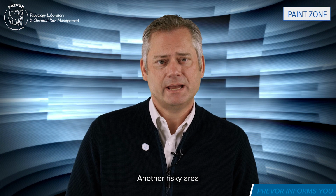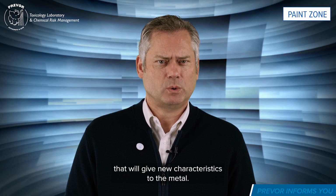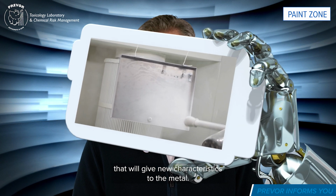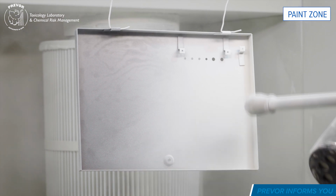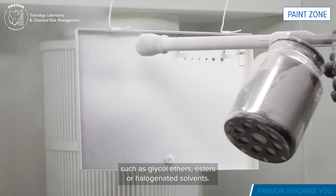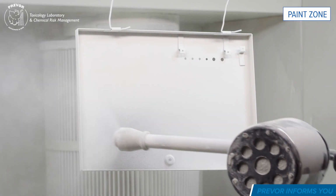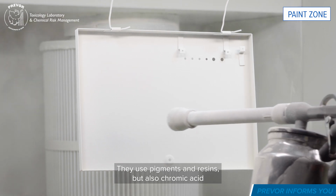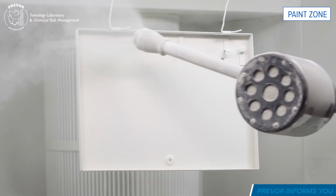Another risky area is the painting and/or application of liquid coatings that will give new characteristics to the metal. This stage involves the use of solvents that can be irritating, such as glycol ethers, esters or halogenated solvents. They give the paint its appropriate consistency. They use pigments and resins, but also chromic acid to obtain generally a mirror aspect.